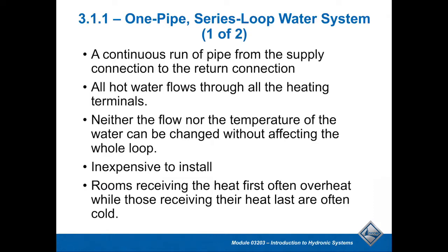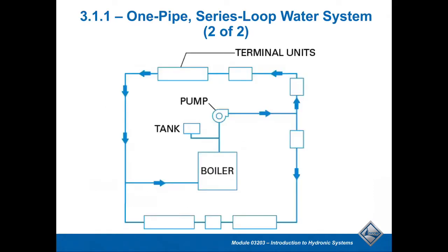The downside of that is if it's not designed right and you end up with too low a water flow, those first units will typically heat up pretty nicely and maybe even a little overheated, but the last units are where the problem is going to be. They typically don't get enough heat. And so we'll take a peek at why.